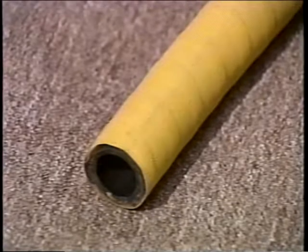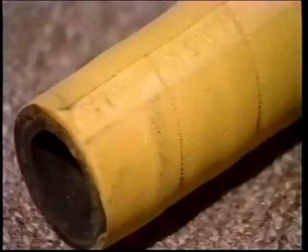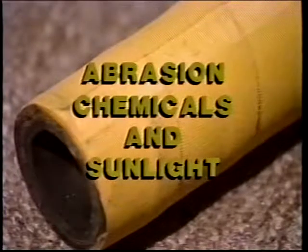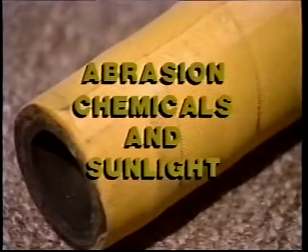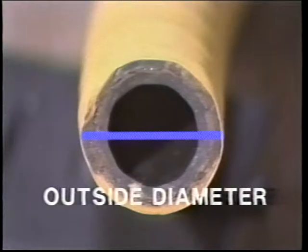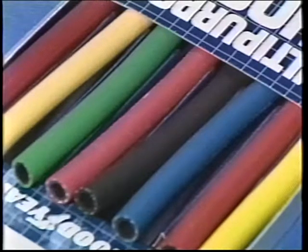The reinforcement of the hose gives the tube the strength to withstand pressure or vacuum. The primary function of the cover is to protect the reinforcement from external damage such as abrasion, chemicals, and sunlight. The cross-section measurement of the outside of the cover determines the outside diameter, or OD, of the hose. The tube and cover are generally manufactured with various kinds of rubber or other chemical compounds to resist damage and to improve the life of the hose.